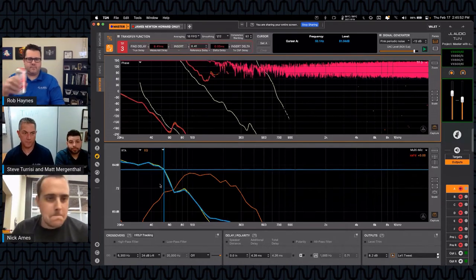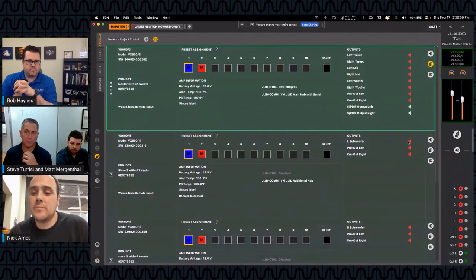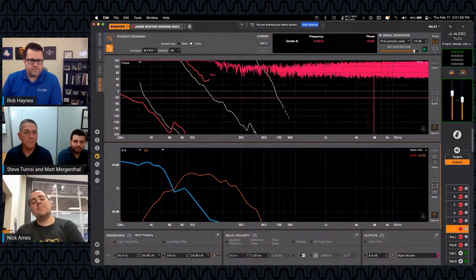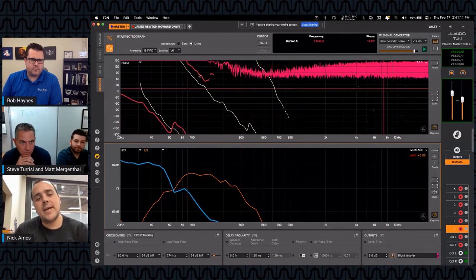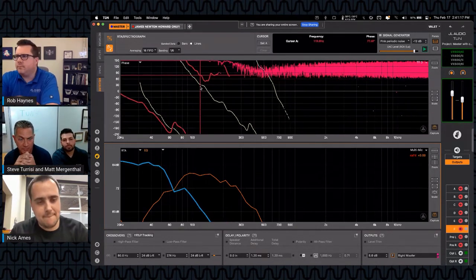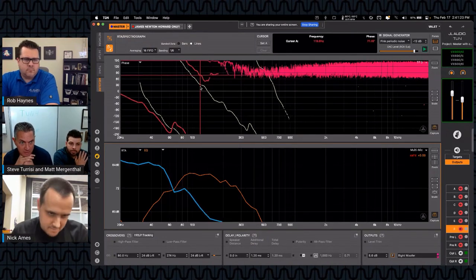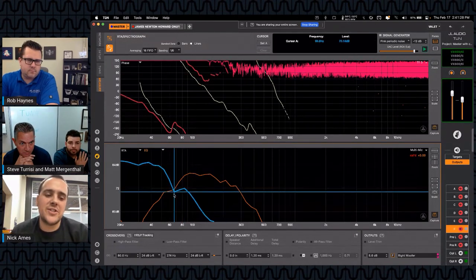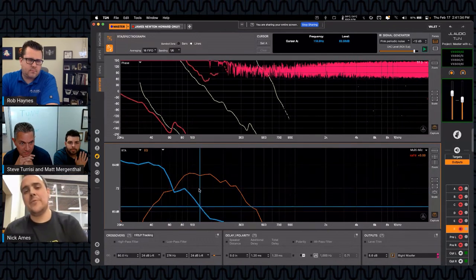No, not at all. So the next thing I would do, I suppose, is look at the subwoofer or subwoofers if you've got more than one. Anyway, our impulse response alignment got us pretty close with these two. Pretty good. So the yellowish curve is the captured pair of mid-bass drivers phase on the top, right? That's that trace. And the red trace is the live data from the subwoofer right now. Yep, exactly. Now this subwoofer has a bit of an unfortunate thing going on where there's this null effect right here, right at the crossover region. That's kind of a bummer.